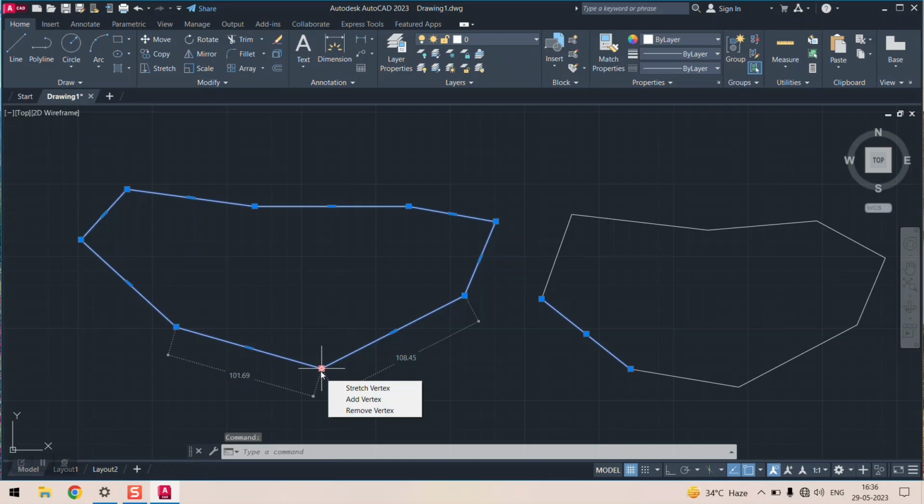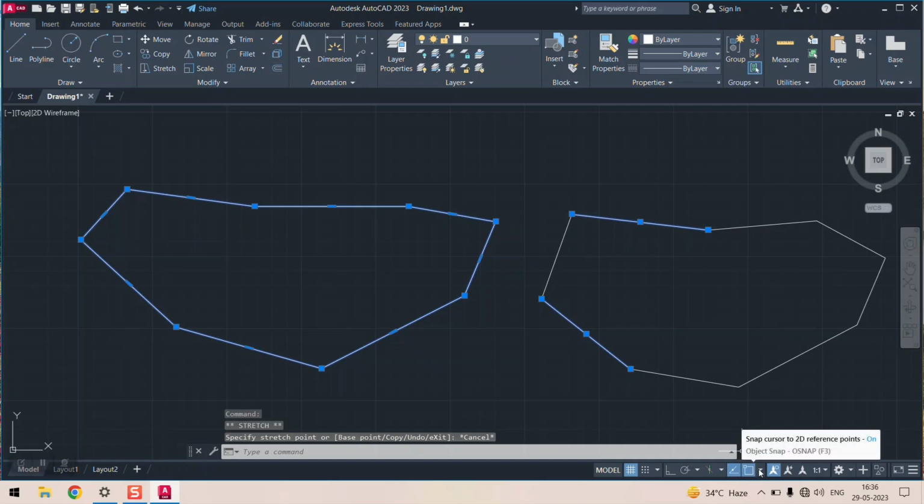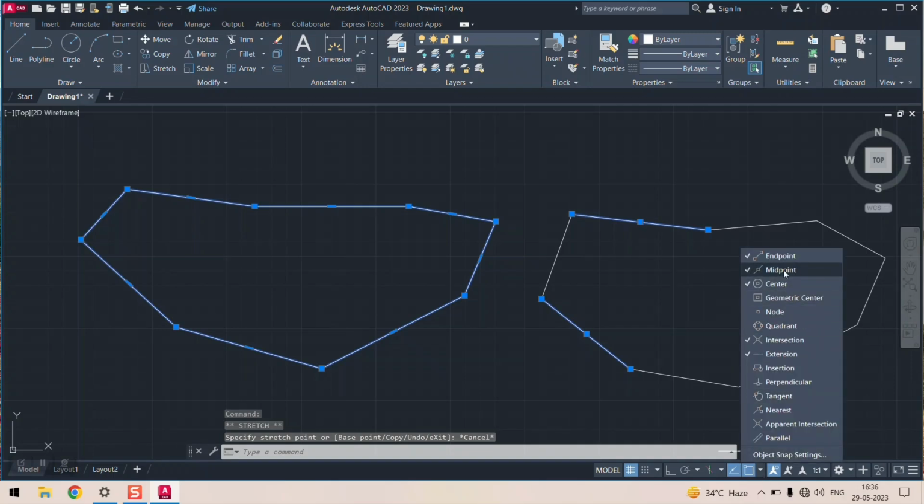In this, this is completely different. You can see the differences between these two. You just go to this, and it will show you the length of adjacent nodes. But in this, if you select this particular line, let us suppose this line I have selected, and you go on this particular center point, it will not show you anything because this is the midpoint. With the help of object snapping, you already allowed it to measure the midpoint of everything. So this is a midpoint, this is also its midpoint, so it will not show the length of this.